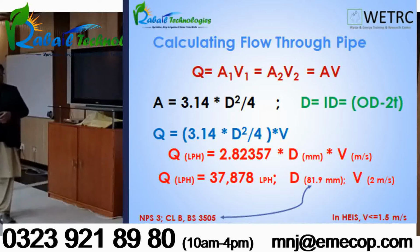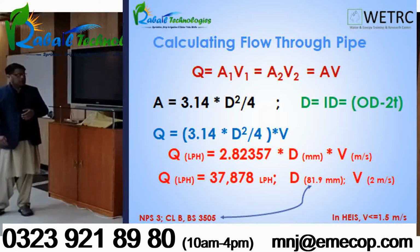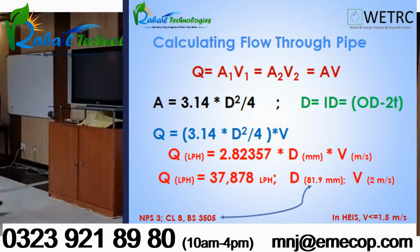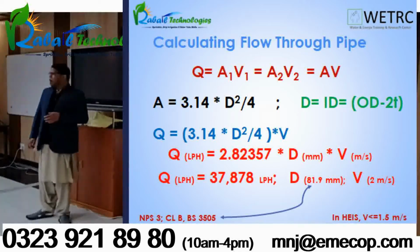Putting all these values in the equation here, we get 37,878 liter per hour. You may have some conversion factor with it, but overall, the maximum carrying capacity of a 3-inch pipe with 2 meter per second velocity will be around 37,800 liter per hour.